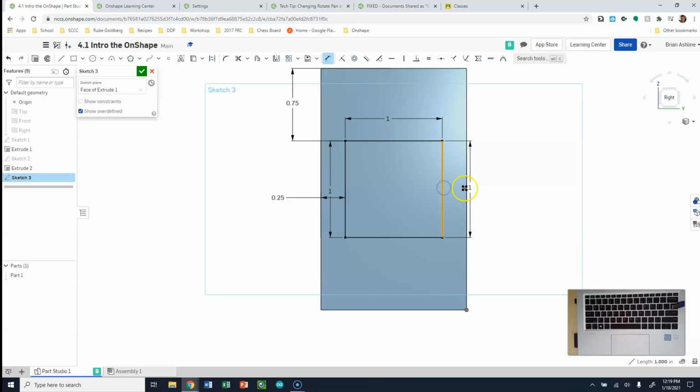So if I want to dimension the opposite side, which a lot of you might find yourselves trying to do, and you set this as being bigger than it should be, it's going to give you an error. That's because the amount of space required for 3 plus 1 plus 0.25 is too much, right? It's like 4 1/4.